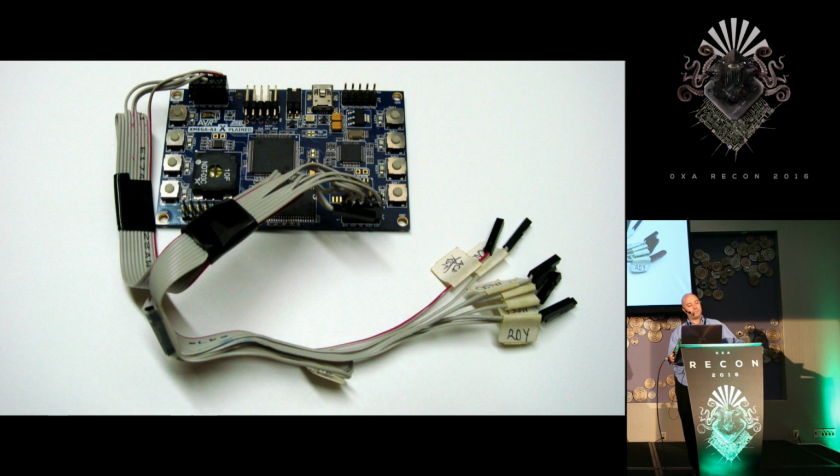To monitor the data passed between the set-top box main controller and the ACP on the SPI bus, I use an Atmel XMEGA development board. I configured two SPI ports as slave, with the master out slave in signal connected to one, and the master in slave out signal connected to the master out slave in input of the second port. So from one port, I get bytes that are sent from the set-top box controller. From the other port, I get the bytes sent from the ACP. If I want to talk directly to one of them, I only have to connect both the pins properly for the SPI, and I can hold the main controller in reset, and then you can talk to the ACP directly without it interfering.